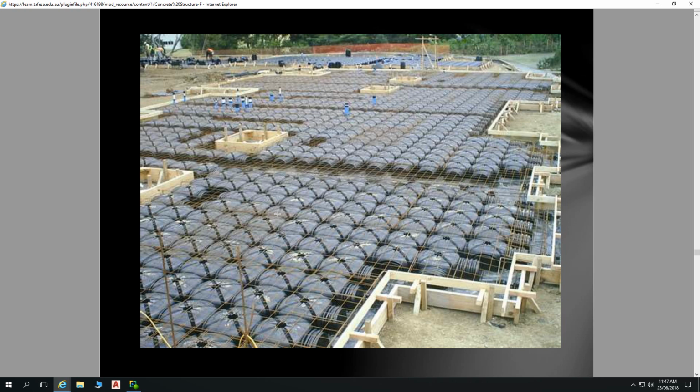Yeah, and it's about going, look, we don't need concrete in this spot. We don't need any compressive strength happening here, right in the middle of that thing. So let's not put concrete in there, because concrete's expensive and it's heavy. Let's put our concrete exactly where it's needed. So that's what these various different void former technologies are all about.